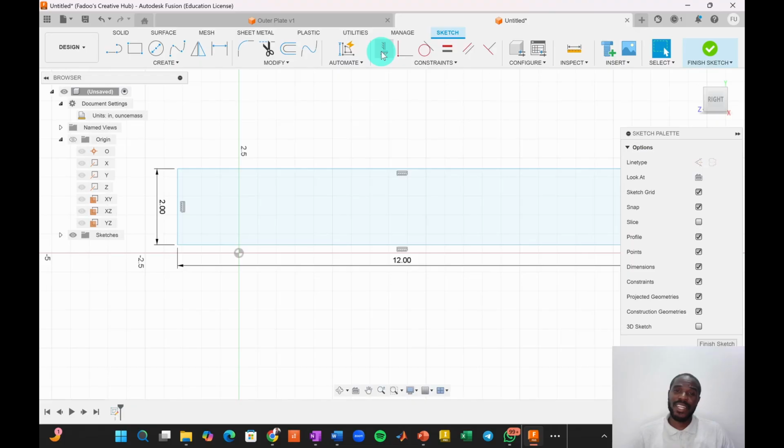Okay. There is a coincident constraint. Coincident says the same point: the same point existing at the same point. I'm going to use that one very shortly. It takes two different points and aligns them to exist at the same point. Then you have the tangent constraint that picks a circle or a curve and a line, or it could be a circle and a circle, to say that these two lines, one curved and one straight, or both curved, touch each other but do not cross each other. Okay, the principle of tangency.